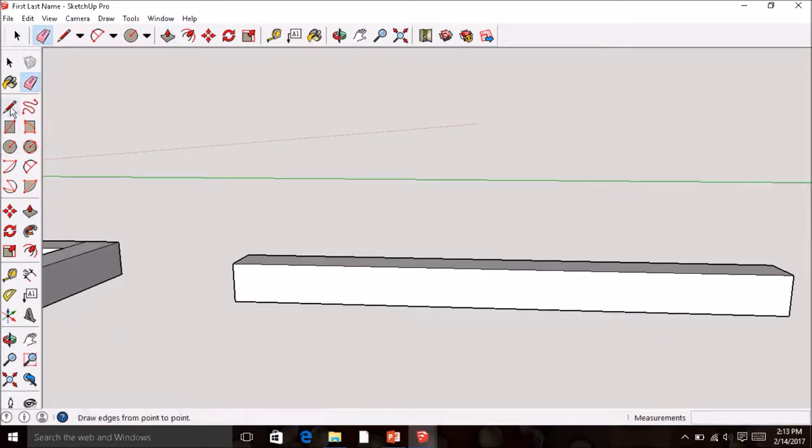And once we're zoomed in on our arm, we're going to draw some holes for adjustment of our dowels and also for hooking to our rubber band and our dowels. So we're going to start by going from the midpoint, coming over 3/4 and hitting enter. We're then going to draw a circle once again at 3/16. So we go 3/16 and hit enter. We're then going to grab our line command and we're going to go over this time 1.25 and hit enter.